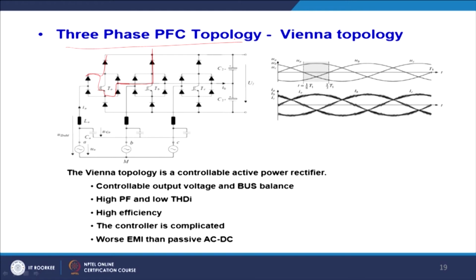These are all power diodes, and while current flows, it accounts for 2 diode and 1 switch losses unnecessarily. So, the 2 diode losses will be around, it is not a 0.7 volt diode, these are all high power diodes, and for this reason this drop will be quite maybe double of the 0.7, maybe 1.5 volt.